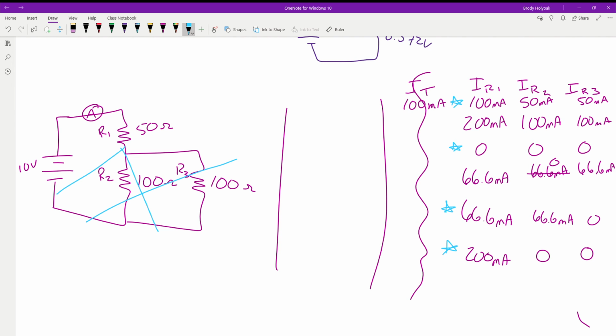Because it won't take 0 if you do the inverse, so you have to do like 0.0001 or something. Just something really, really small. That's the other way you can do it, because you're going to have some resistance with a piece of wire, not much, but there is going to be some. And that's what we're going to find out with inductors, because all an inductor is, is wire that's been wrapped around a core lots and lots of times. So you're going to have 75 feet of wire in a little package this big.